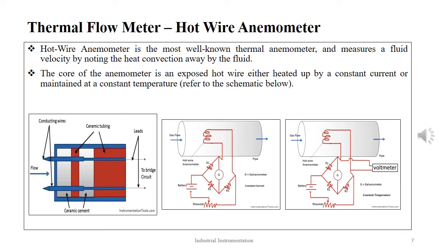Typically, the anemometer wire is made up of nickel, platinum or tungsten and is about 4 to 10 micrometer in diameter and 1 millimeter in length. For commercially available hot wire anemometers, they have a flat frequency response less than 3 dB up to 17 kHz for average velocity of 9.1 meter per second, 30 kHz for 30.5 meter per second and 50 kHz for 91 meter per second.